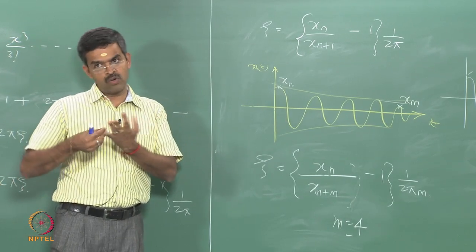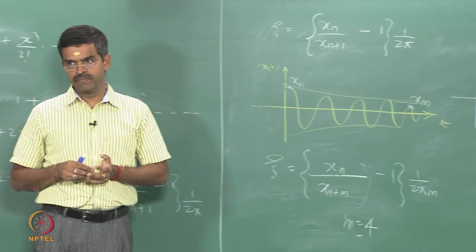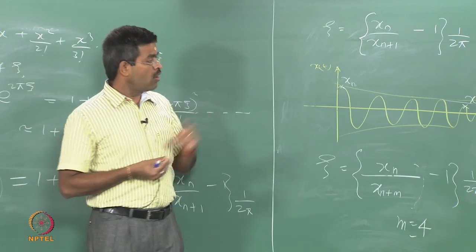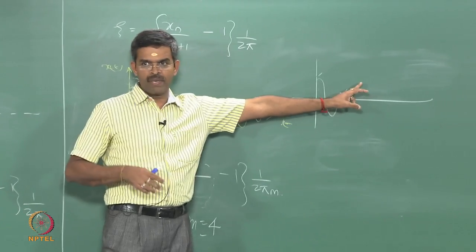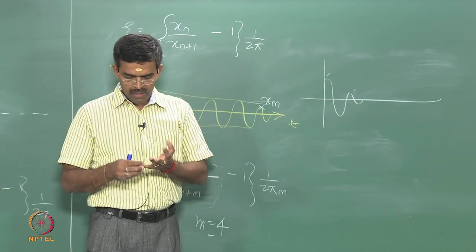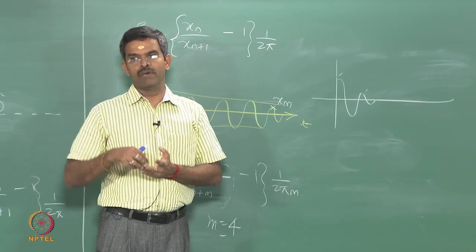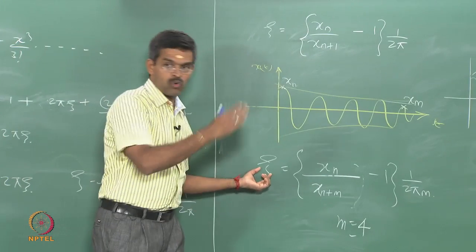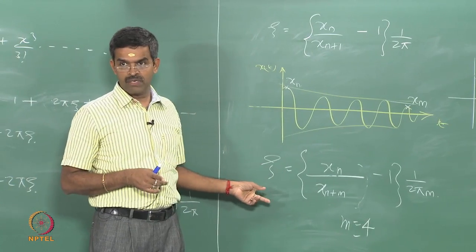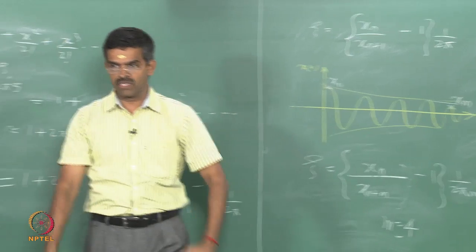Damping source can come from hydrodynamic, can come from air. It also, the system is designed to a recentering configuration, therefore, damping is present in material, in structural members, in the environment. There are various sources. So, you will not be able to get the damping of different sources separately from this equation. It will give you the overall damping of the structure.